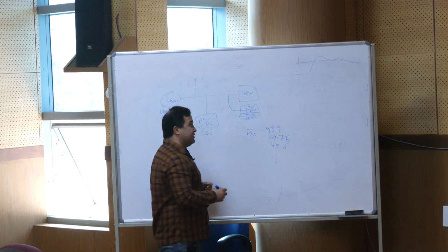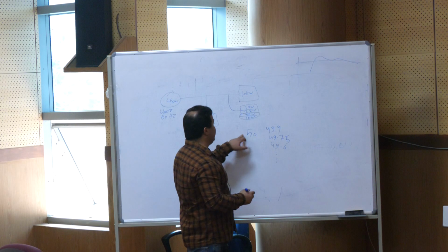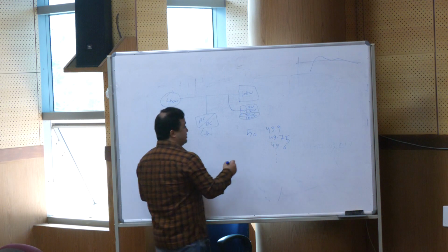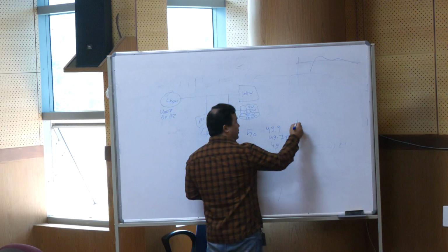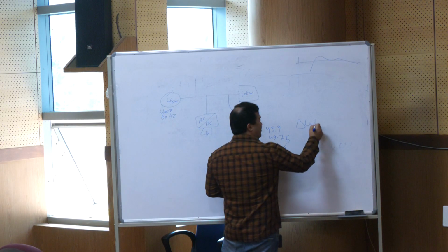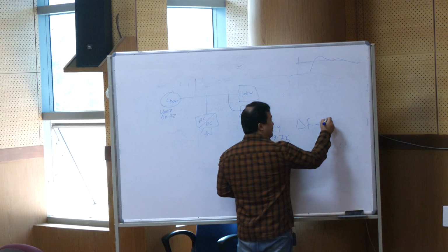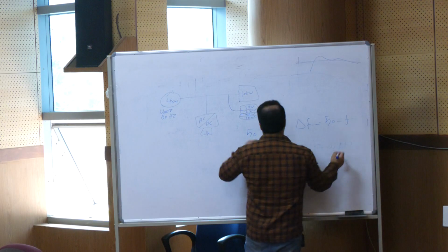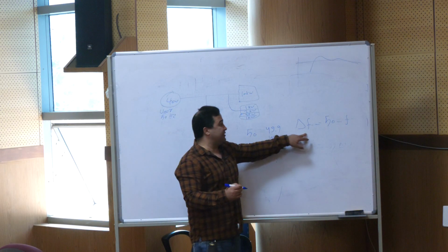So how do we understand that now we should increase the active power? We see the frequency. The frequency is 50 hertz minus the change happening in the grid frequency, so we have the delta.